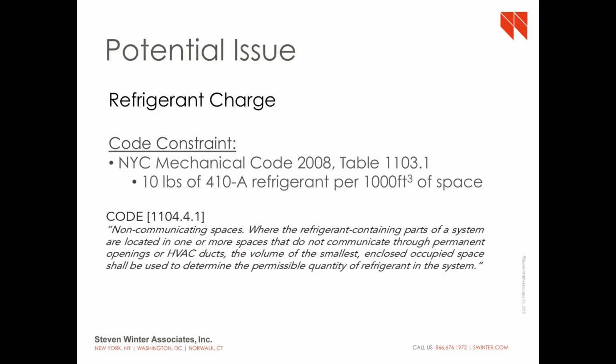The first cost is high, and then you might have some limitations with refrigerant lines, where they can go, where they can cross, and how much refrigerant is in the lines due to the length of it. So that's just a code issue. We had to deal with this code issue. The code's changing, making it a little bit easier to run long lengths, but still it's something that your mechanical engineer is going to have to look at for you if you're looking to do this. Okay, that's just a heads up on that one.